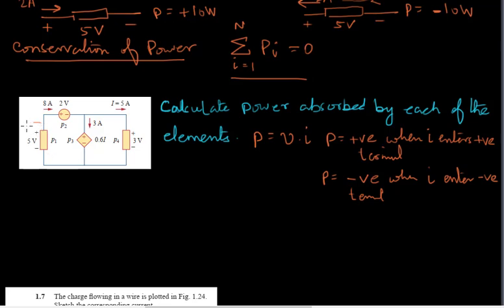So for this element over here, you can see that this branch has this current flowing, which is 8 amperes. You can see that the current is going up and then going right. So some current enters the negative terminal. If that 8 ampere going up is shown over there, it means it must have come from here. So 8 amperes must have come from the bottom, which means the current is entering into the negative terminal.